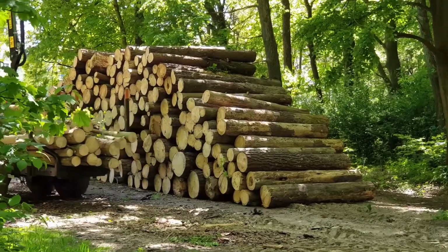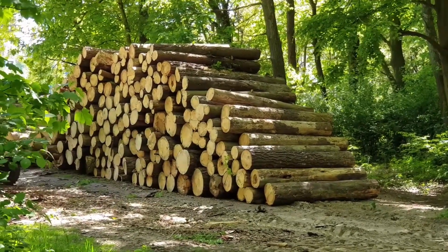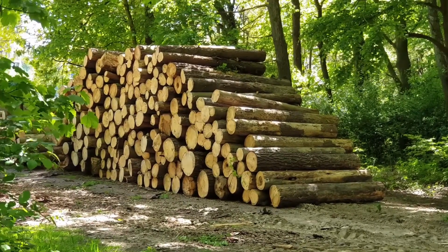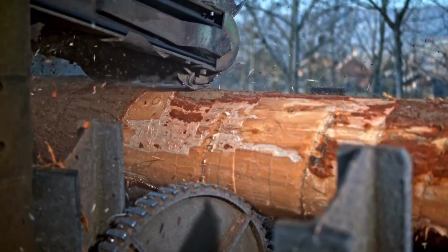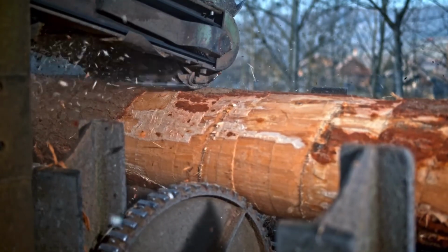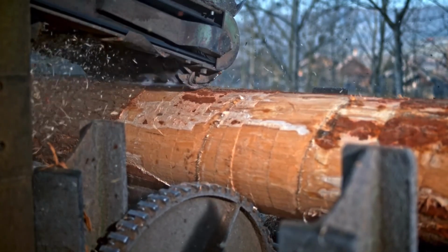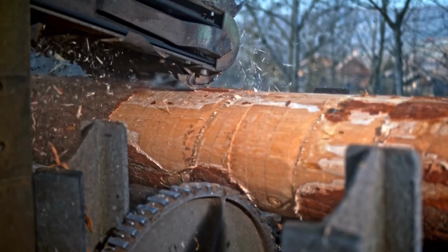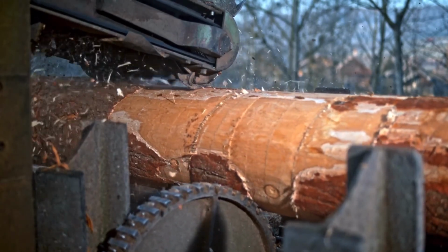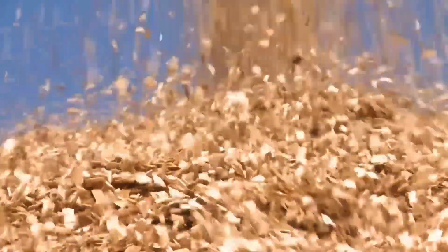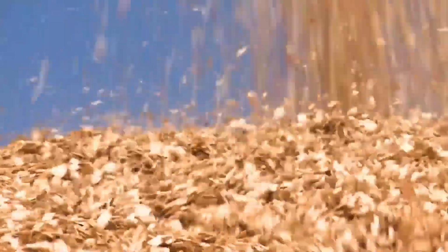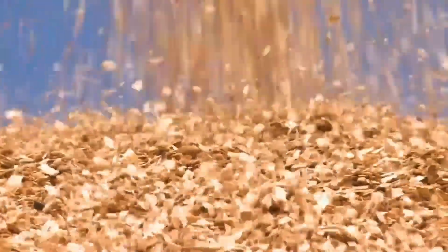Papermaking actually involves various processes to turn the wood log into everyday paper products. However, there are three key steps to the process of papermaking, namely pulping, papermaking, and finishing. To kickstart the pulping process, the logs are debarked. The bark has to be stripped from the log since it cannot be used in papermaking. The debarked logs are then chipped into small pieces before undergoing a process called chemical pulping.